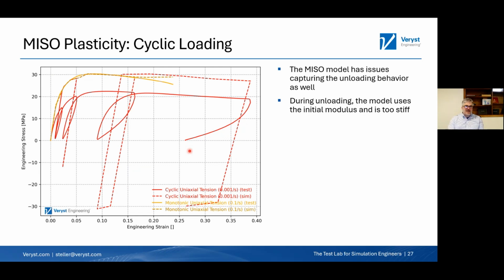So it's that same HDPE model, that same HDPE material, and the red curve we've done at a different strain rate, and we've done some unloading where we went to 5% strain, we did some relaxation unload, and then we went to 15 and 30 or 35. I did that same thing. And the red line is a prediction there. And this is what metal plasticity would predict.